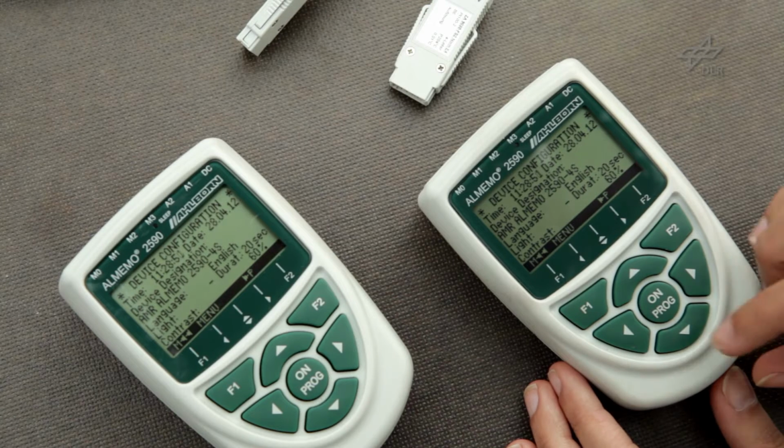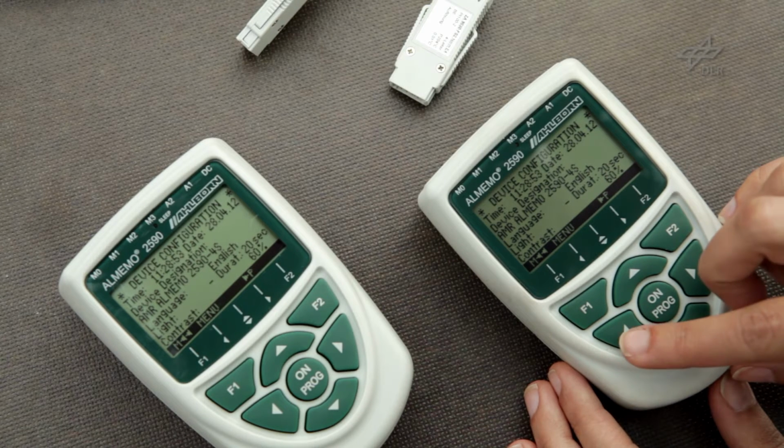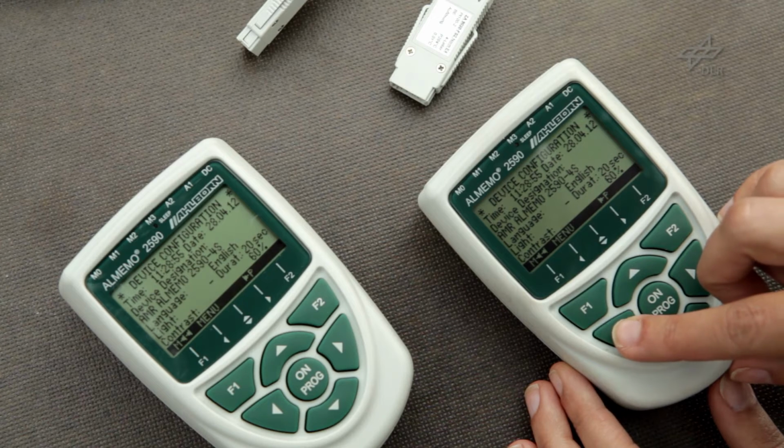Furthermore, test campaigns involving many signals may require several devices for data logging. It is vital that all internal clocks of those logging systems be absolutely synchronous. Only then can the data points be referenced by their timestamps.